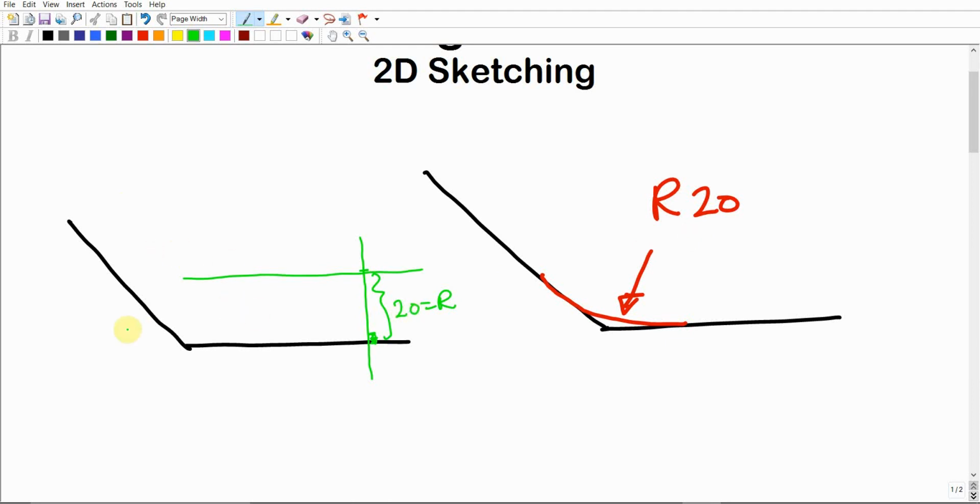Repeat the same for the other line. So, from any point, draw a line that is perpendicular to the other line, and make sure that it is completely perpendicular. The accuracy of the dimensioning and the measurement is very important. If you mess up anything, if your calculation and measurements are not accurate, the curve, even if you spend the whole day, won't be touching the two lines. Make sense? So make sure that this one is completely perpendicular using the set square as we discussed before and practiced in the class, and as I'm gonna show you by hand through this lecture.